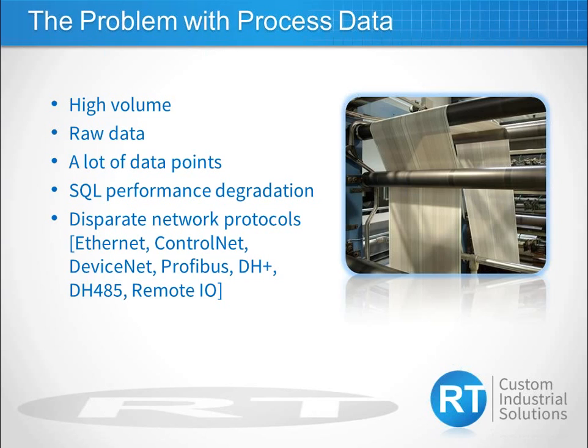Well, at some point you may have a high volume of it. The other one is raw data itself. If you're grabbing every single data point, it's really not a true representation of the process. You may have to filter some of that out, because you're going to have peaks and valleys inside the raw data. SQL Server is a great thing. It's a very well-used tool, but unfortunately, the performance degrades over time. SQL Server works great when it's small, but if anyone out there is a database guy, they'll know that as the SQL Server database grows, performance decreases.